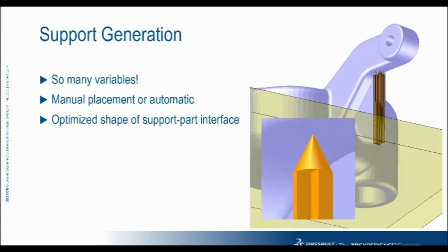But the actual process of creating the supports can be varied a lot. You have different geometries that are preferred for different materials. Different users will develop a favorite, right? They like straight column supports, or tree-shaped supports, or solid supports, or hollow supports. So many possibilities. The important thing here is that if you have a strong 3D modeling engine available to you, then this application can make supports as complex or as automated as you want to offer to the user.